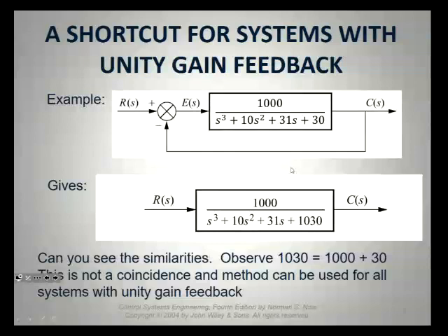But when you're doing your steady state errors, you always have to put your system into this equivalent system with a unity feedback. And then your analysis of your proportional gain, position constant, velocity constant, and acceleration constant is done on this system. But it has to have unity feedback. You can't do it on that system if there's a transfer function here. I can't remember if I told you that or not. Anyway, we'll go over it in revision.